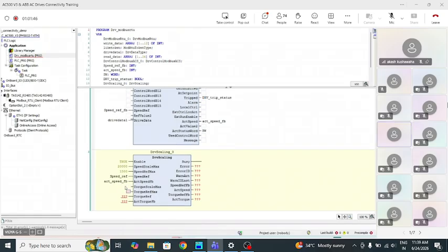If you're using torque reference, you'll do the scaling here, 0 to 10,000, 0 to 100%. Here the speed feedback reference I will be using. Whatever you feed in here, for example, if you give 1500, it will show the scaling in 20,000.